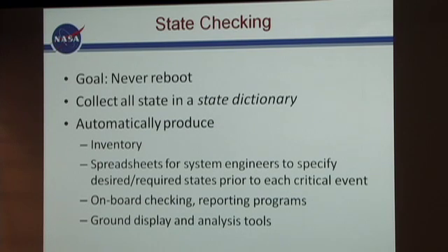Another reason for doing a reboot is that, for example, for EDL, which MSL did do a reboot, I don't know, a few days ago, cold boot of everything. Why would they do that? There was no reason to, except nobody knows what all the state is in the spacecraft. And the theory is that, well, every time we tested EDL, we rebooted the test system and the flight computer that was a part of that test. Just in case there's something going on that we don't know anything about, because we don't know all the state in the system, let's do a reboot and hope that if there was a problem, maybe the reboot will cure it.